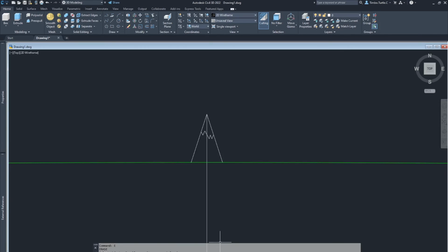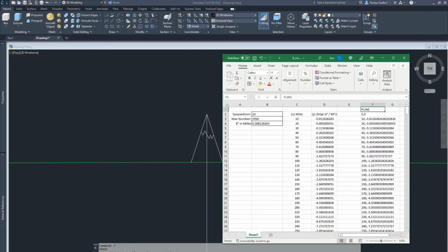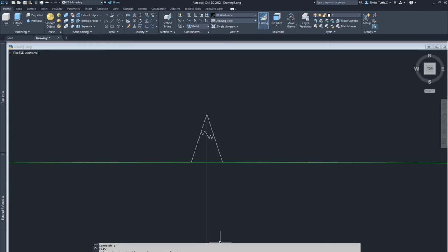So coming back to here, we come down to here. All I've done here, if you put in the commands in order in Excel, AutoCAD assumes that each new line is a command. So it would be the same as me typing in pline, enter, then it would ask for the coordinate, then ask for the next coordinate, then ask for the next coordinate, and so forth. So that's all it is. There's nothing overly fancy, but it just saves you a bit of work.